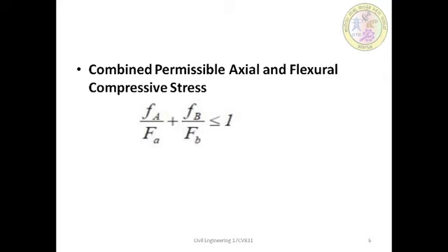In the interaction formula, the secondary effect of moment magnification for the flexure term due to axial load is not included, which is an error on the unsafe side. However, this error for practical wall sizes will be relatively small, and the overall factor of safety of around 4 is adequate to account for this amplification of the flexure term. The code allows a 25% increase in allowable axial compressive stress if it is due to flexure.